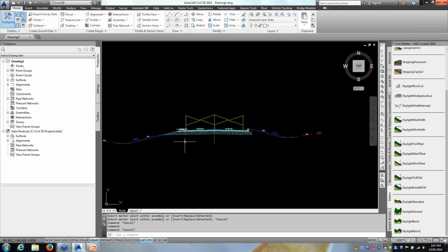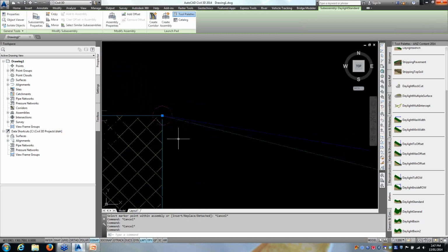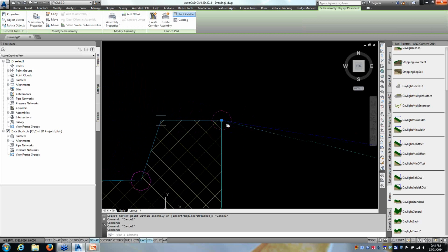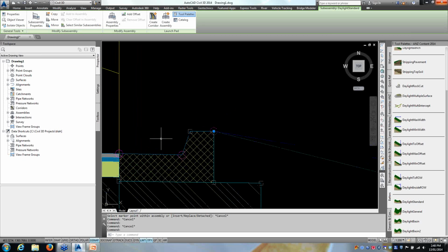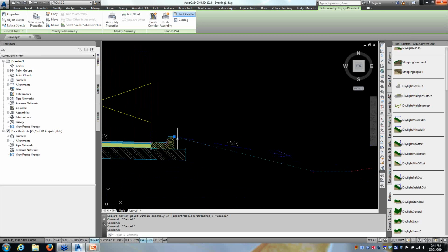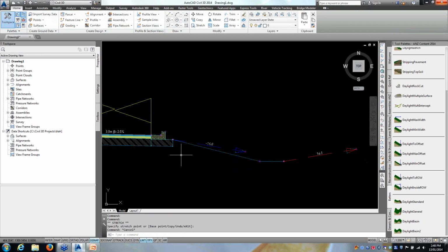The thing about putting these things together, and you may have noticed when I snapped them together, was that I picked on these little red circles and grey squares to snap them together. And you snap them together like Lego. Those are like little tongs on the top of Lego. If you want to move them again, don't grip edit them. That is, don't pick one, find this grip, and move it down to here. Okay, the reason being that the software still thinks it's attached up there.